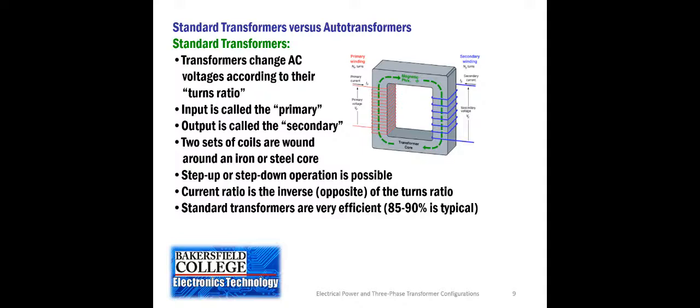The first reason is that we don't have superconductors. We have wire that has some resistance to it, so a resistance will have a voltage drop across it. That voltage drop is a loss of voltage or pressure across the wire. And then in addition, we have inductive reactance, and those things tend to limit the current and also tend to use up a little bit of the power that is created. Now, if you wanted to go with a delta instead of having the Y connected secondary, you had a transformer that had the delta configuration for the secondary connection. One of the things that happens is that a three-phase transformer is built as three transformers all together as one unit.